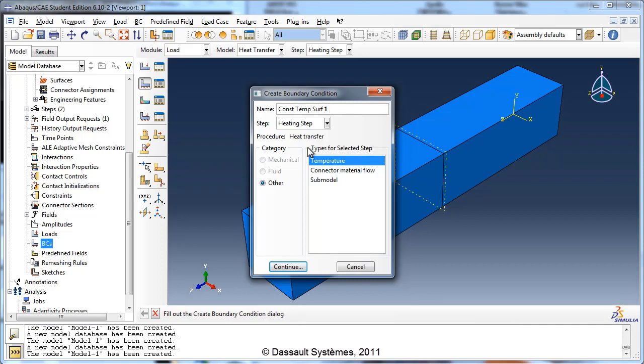However, this is not possible in this procedure because Abaqus will not let you apply any non-zero boundary conditions in the initial step. In previous tutorial videos, our boundary conditions have involved fully or partially constraining the instances by setting either a few or all of U1, U2, U3, UR1, UR2, and UR3 equal to 0, depending on which degrees of freedom we wish to constrain.